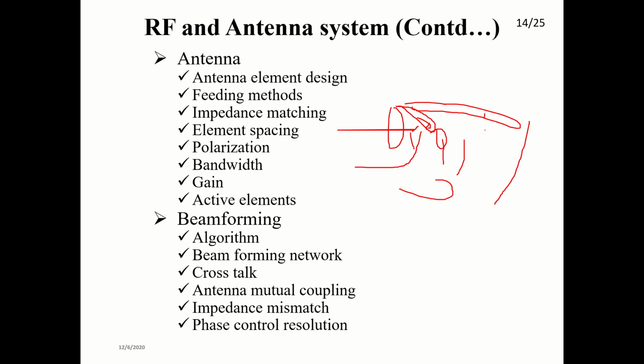Achieving impedance matching is very difficult in 5G especially, because here the antenna is not alone. When you want to match with 50 ohm, that's okay. For papers we always used to design for 50 ohm, but that is not the case in 5G. If you design for 50 ohm, then the output of the amplifier will be a different ohm, and then you have to go for matching networks. So multiple things, it will be an iterative process.